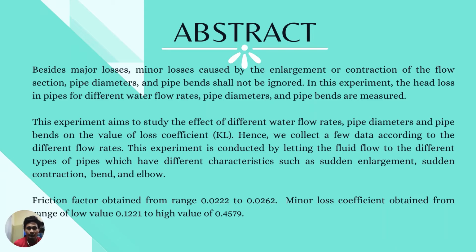So for this experiment, we are measuring the head loss in pipes for different water flow rates, pipe diameters and pipe bends. The purpose of the experiment is to identify the effect of different water flow rates, pipe diameters and pipe bends on the value of loss coefficient, which is KL.